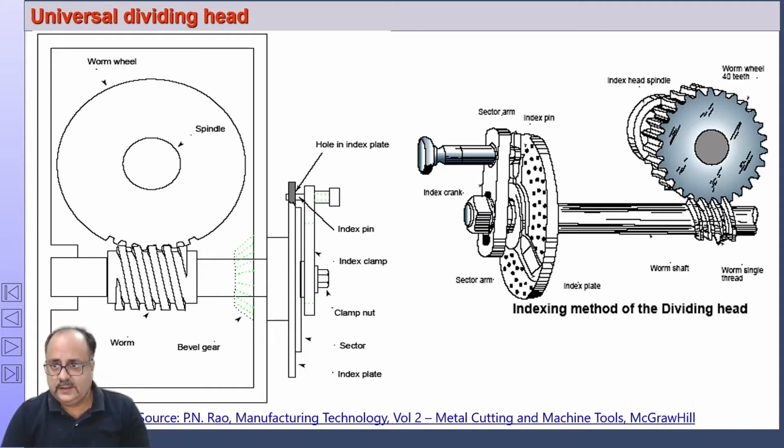This is the standard, but there is no particular reason why it has 40 teeth. Please remember this construction of the universal dividing head.